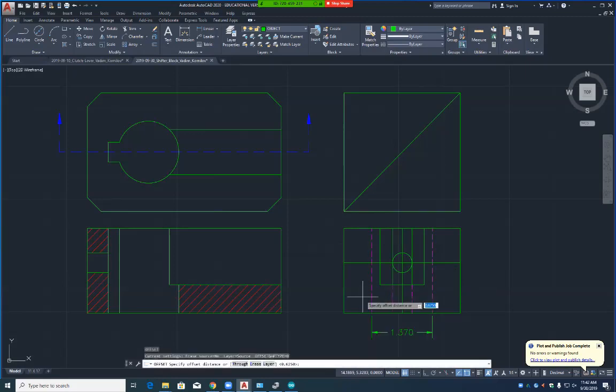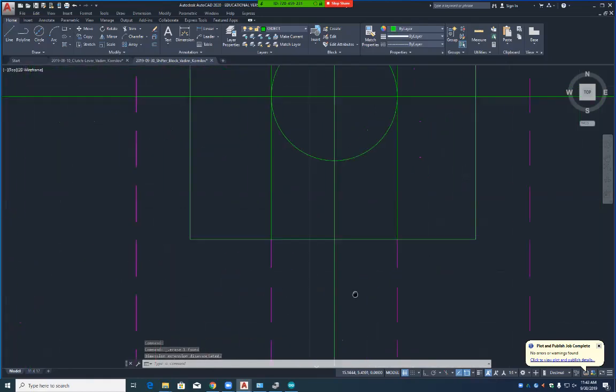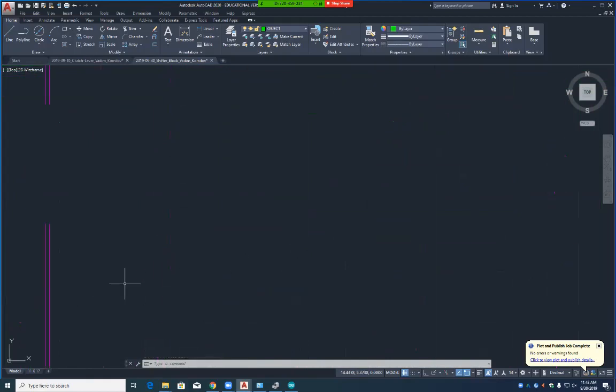In a section view, this is a section view, isn't it? Center lines, it is not a requirement to have center lines in, but a lot of people put them in because of clarity. So I always put center lines in my hatched section view. And you can get those easy enough. You can just project it down, can't you?